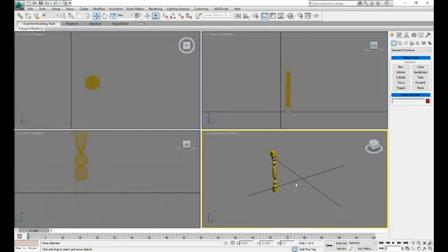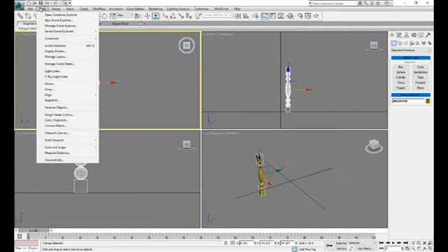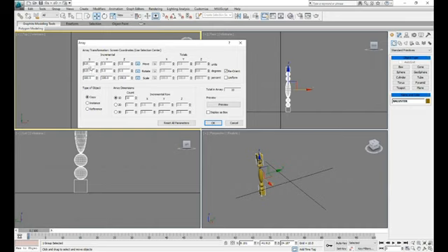If I will say the balusters in the stairs, all you have to do is make a lot of things like this. So check what happened. I will click here, tools. I will use the command array. I want it in the x-axis. I want it every 0.3 meters. The count is 10. Check what happened if I will click OK.